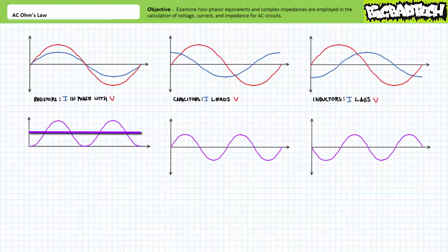Recall that the 2 bursts of positive power dissipation can be averaged to arrive at an average power dissipation figure over time. Not so for reactive elements like capacitors and inductors. Given equal periods and magnitudes of consumption and supply, it could be rightly said that the average power dissipated by these reactive elements over time is 0. What does this mean in terms of power, given these reactive elements continually draw current?